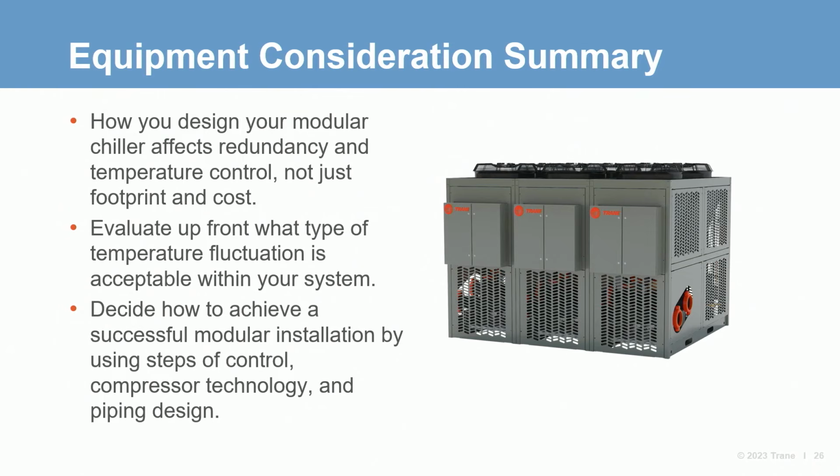My final thoughts on equipment considerations are simply to focus on the upfront planning of your modular chiller. Now that you understand how compressor staging works between different modules, you can use this as a tool for determining how many and what type of modules should be used in your chiller plant design. Sometimes this may also mean incorporating hydronic components such as valves and tanks in the chiller plant for overall effectiveness. Make sure all the needed hydronic and control components are in place so installation into your system goes smoothly.